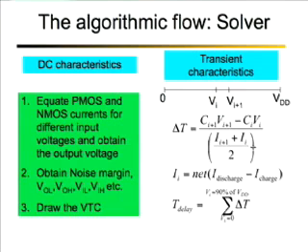So delta t is given by C(i+1)V(i+1), which is the charge at point i+1, minus the charge at point i, divided by the average of the current that flows in this voltage range. And the I would have to be the net current, which is the net discharging minus charging current if we are looking at discharging the output node.